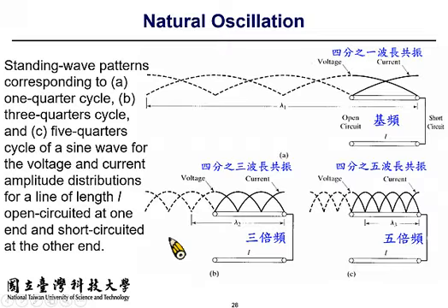So that's one way to formulate a resonator. And you know that the resonator only resonates at a certain frequency. For this example, this is a transmission line, and at the so-called fundamental frequency, that is the lowest frequency that a resonance can reside on this piece of transmission line, which has a short termination at the right end and an open termination at the left end, the length of the line happens to be a quarter of a wavelength.